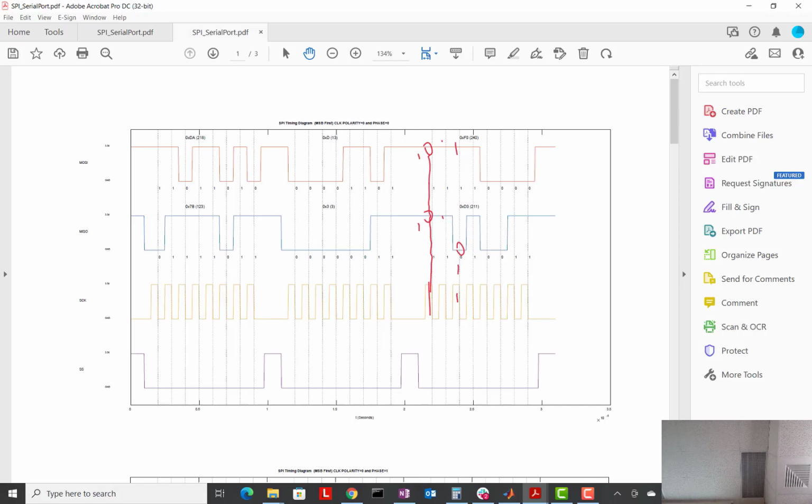For the baud rate, it's the bit rate. This amount of time, a full clock cycle, is the bit rate I'm asking for. You're just going to estimate it. It does not need to be exact. I give you the units right here. You can't even see them, but just guesstimate. It's from 2.5 to 3. I think that may be 10 to the negative third. I don't know, I can look here. That is 10 to the negative fourth. So this amount of time, you guesstimate what that is, and give me a bit rate. Agreed?